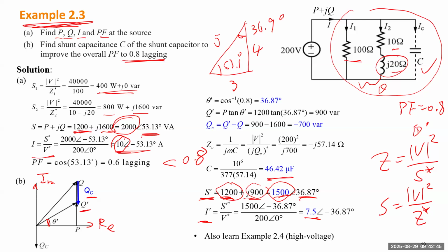code. For instance, what if you improve the power factor to 0.9, or even to 1? 1 means complete compensation. So you have a capacitor fully compensate the reactive power of that inductive part. Yeah, so you can try that to see what changed.